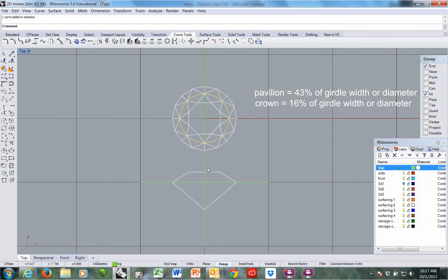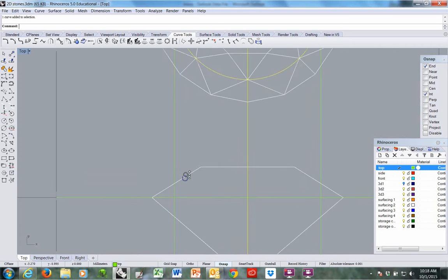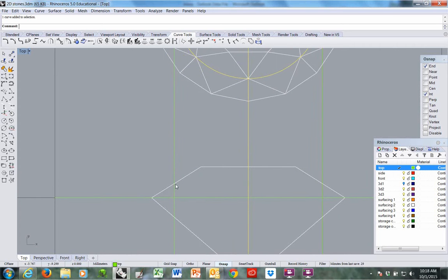Back at it. So, I know that the widest point of this line is right here at the point of the star facet. So I'll go ahead and offset a construction line that distance. Through point, both sides. Oh, meant to, sorry, this curve. Through point, both sides. And that carries the width of this line down to here. I need to find its actual location along here though. And this is not midway. This is farther down. You can see that.